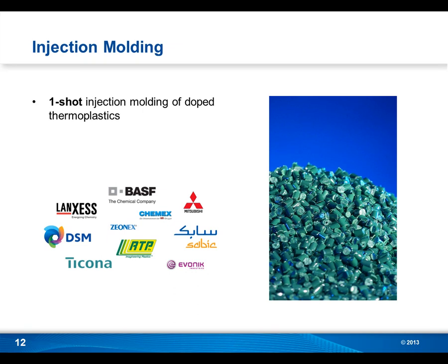Unfortunately not. I hate to say this, but no, it's not, because we put a catalyst into the material, and I have not yet seen any plastic resins or LDS grade resins that are clear. The catalyst is almost like a color additive to the material, and of course it creates different colors. Most of the materials are black or dark gray. There's some materials that have blue tones or that are white materials. So there's some variations to it, but unfortunately there's no clear material.